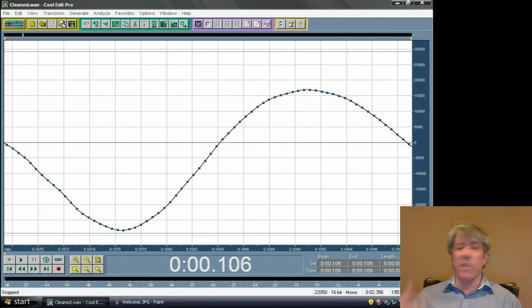Let's make the math easy. Let's say it's 1,000 with 10-bit. You can make that range of 100 degrees divided by 1,000 is 1/10 of a degree you can measure, which is doggone good resolution most of the time for most processes.